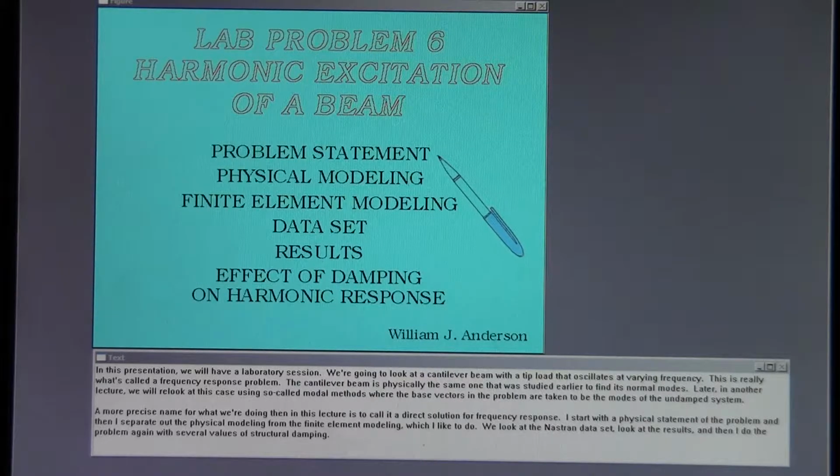I start with a physical statement of the problem, and then I separate out the physical modeling from the finite element modeling, which I like to do. We look at the Nastran data set, look at the results, and then I do the problem again with several values of structural damping.